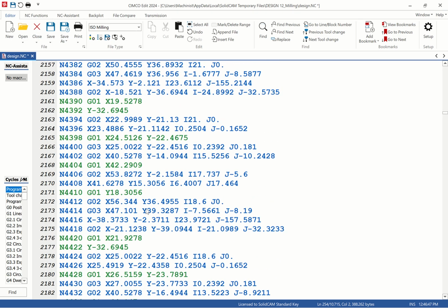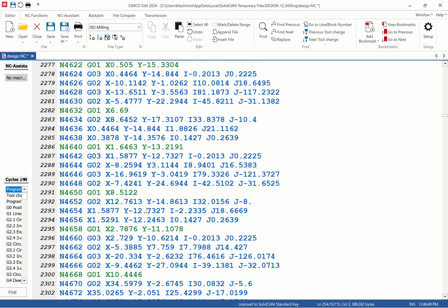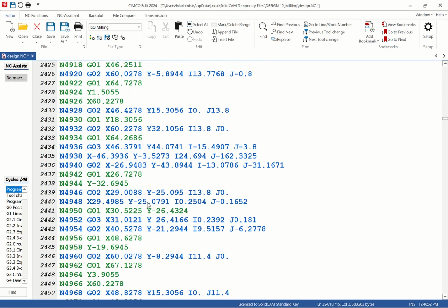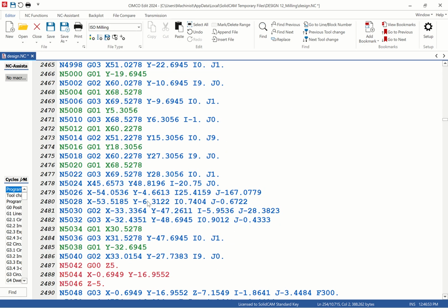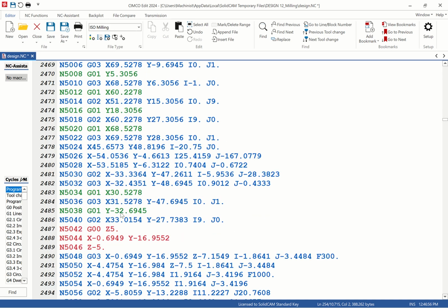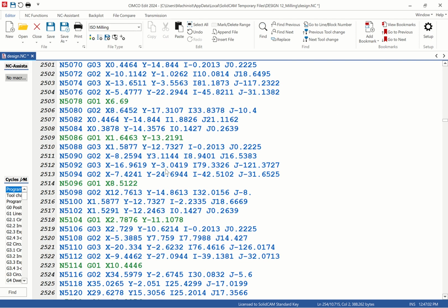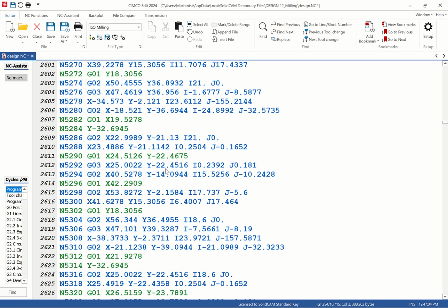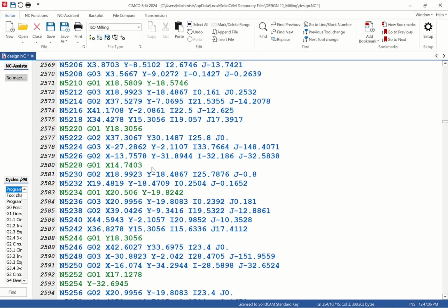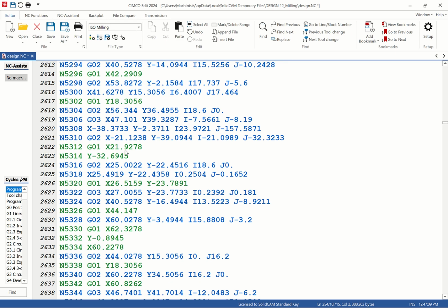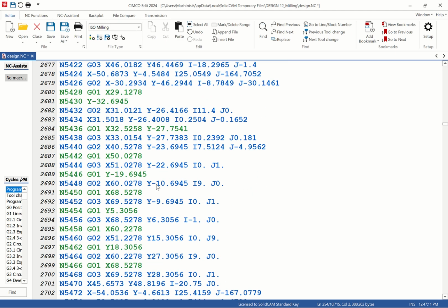So you can use find, but I want to go direct. No problem, don't worry with this. So this is a combined program. All this where you see these different colors, that's put all the program. Like the red is not cutting, just approaching. The red one is retracting. Then the green one is G01. Then the others are G02.